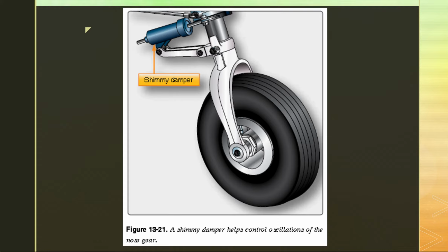Ideally, when you do your takeoff roll, you don't have full elevator down, shoving this nose wheel into the ground and getting the propeller close to it. So a good general habit is to put a bit of neutral elevator as you apply the throttle for your takeoff. That way you're not shoving the nose down. You're more in a kind of neutral buoyancy, if you want to think of it that way. You're not putting any extra weight on the nose wheel, and it will thank you for it.